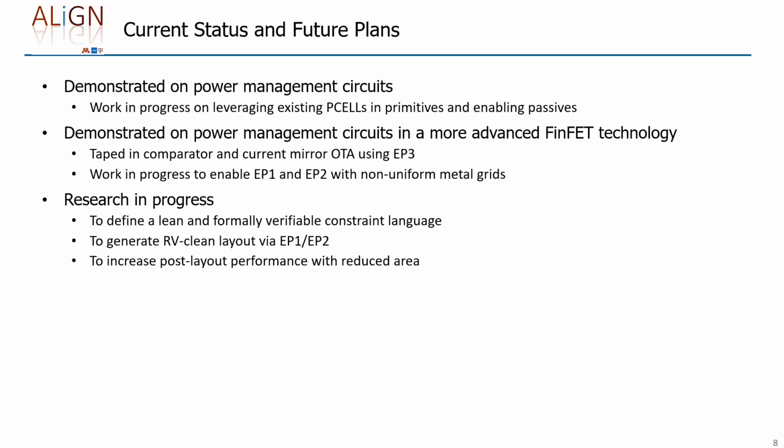This is especially a harder problem in advanced FinFET. And again, using entry points 3 and 4, the user has a lot more control, and it's a little bit easier to achieve this, but there's still some room for improvement on the more automated entry points. And finally, we always try to improve the layout quality, basically push the performance with a smaller area footprint. And that's all I had to share.